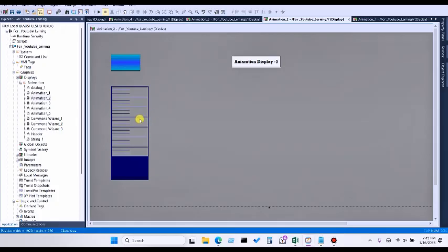So how you can take an analog tag, I already explained in my previous video how you can use a PLC tag, means how you can use an HMI tag if you don't have any PLC, or you want to learn SCADA, so you can make a tag directly in the HMI tag. And for this you want a slider.